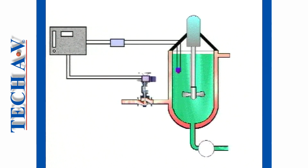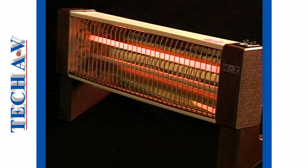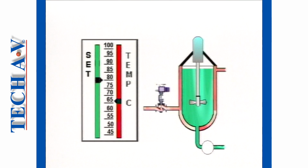Let's study why this is likely to happen. Remember that in our old batch process, we had a large container in which the product was blended. We can liken this to an electric bar heater that is trying to warm the air in a room. Should one decide to increase the heating, then we would set the heater to its high setting, which then takes quite a while for the effect to be felt, owing to the volume of air in the room. In a similar fashion, releasing steam into the steam jacket results in a slow temperature rise of the product.